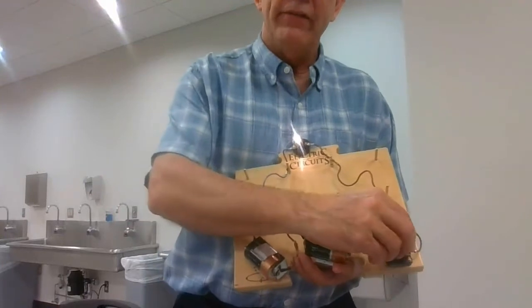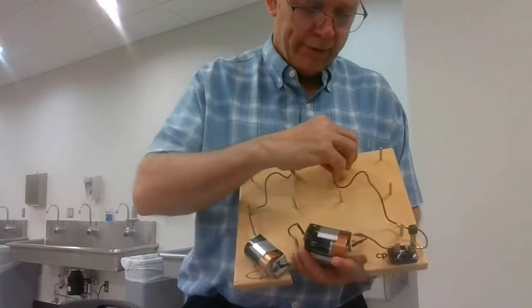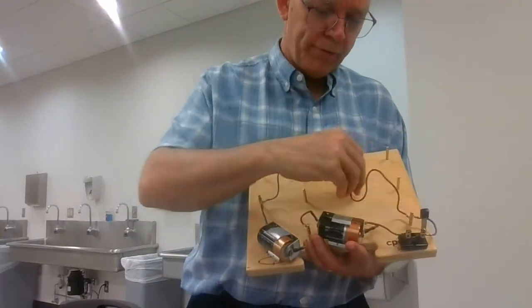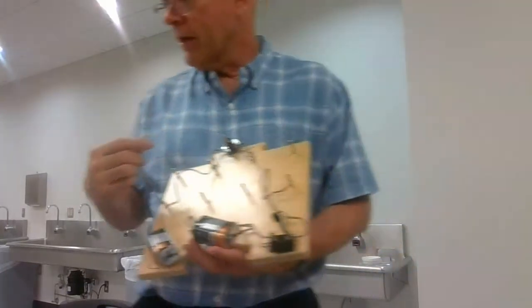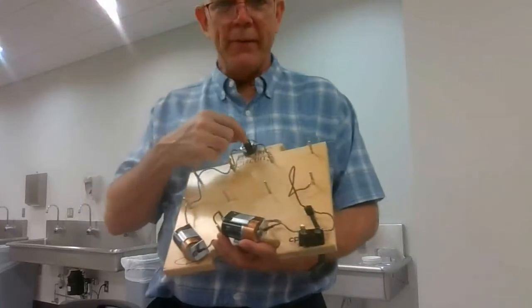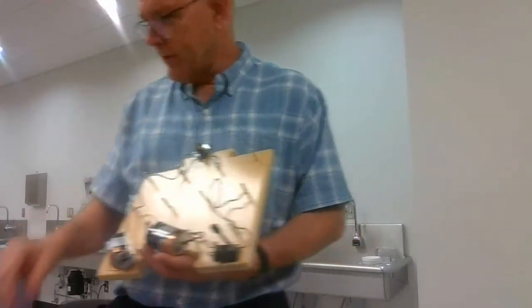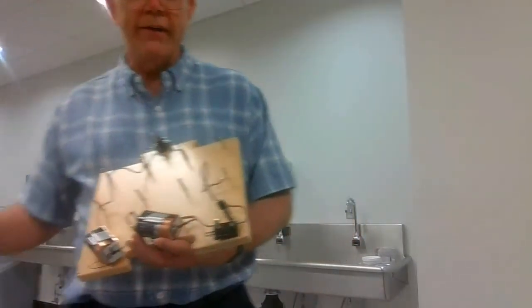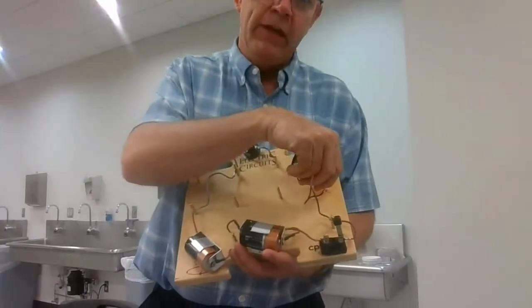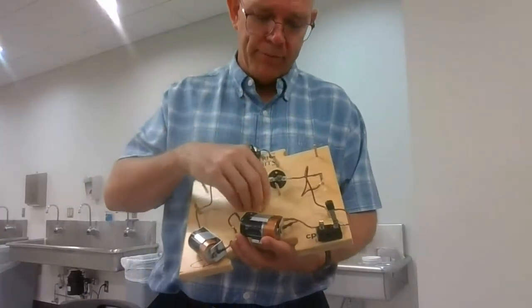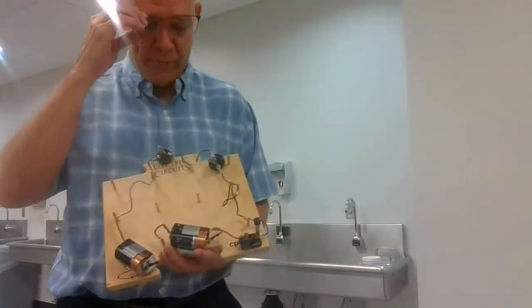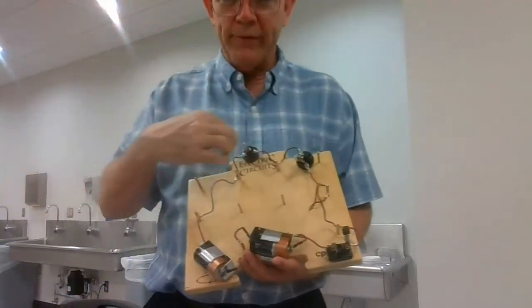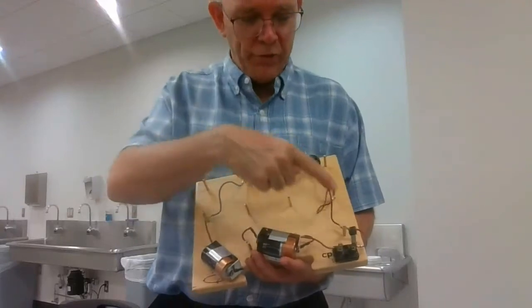All right, now say we wanted to take this off now. So basically all 3 volts is going to that one light bulb, okay, and we would divide that by the amount of resistance of the light bulb, which I don't know off the top of my head, and we can figure out how much current is going through it. Now, but if we put another light bulb, now we have 2 light bulbs, okay? 2 light bulbs going through here. So it's going to go through this light bulb. Notice there's still one path.